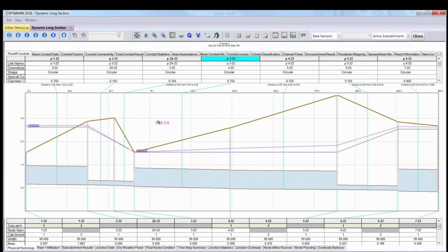The magenta line here shows the impact of the hydraulic grade line, and at times the relationship with the 2D. So where we see this marker in a 2D model means that water has been passed across to the 2D model. So that is a safety. If you've got a 1D model with the dual drainage functions and you see these waves, I will say that is a huge warning. You'd want to review your model because you could be losing water from your network and affecting your calculations quite seriously. Can be quite an important loss.